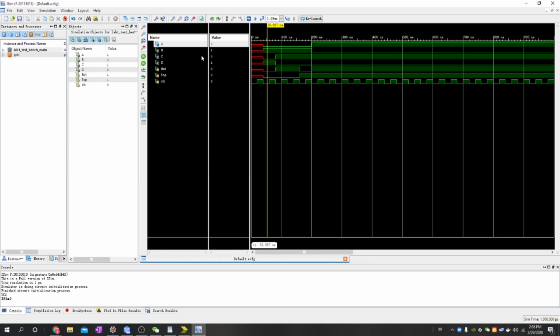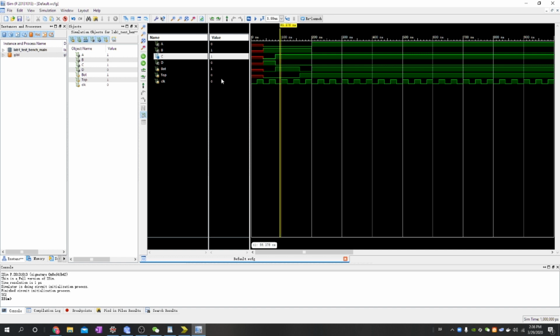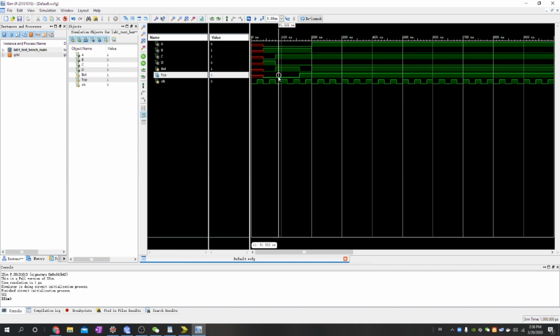The output C is from an OR gate. So in this situation, the output should be 1, and the NOR gate is the inverse of C, should be 1. In the next cycle, our input becomes, I think, 0, 1, and then our AND gate A should still output 0. The inverse of A, B, should be 1. Our OR gate switches to 1, and NOR gate switches to 0. Yeah. So your simulation should be exactly as this one.